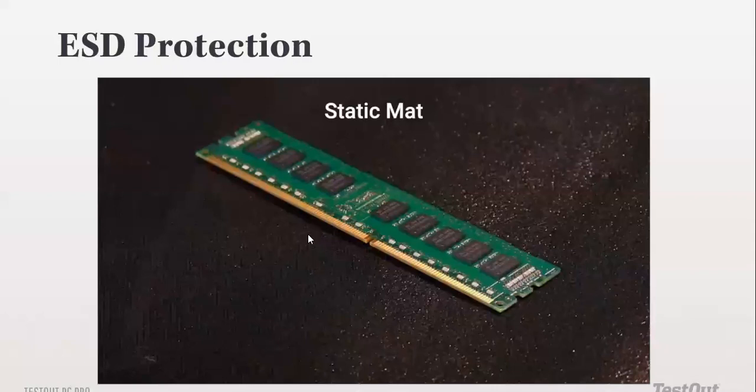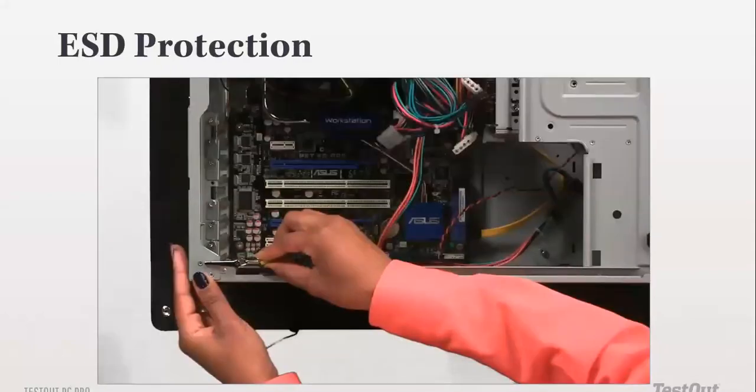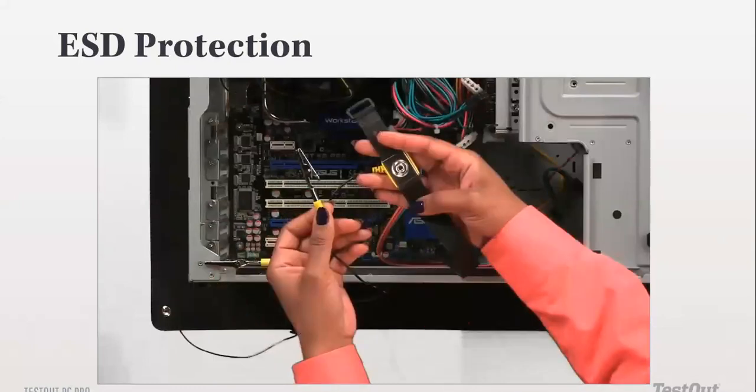There is also another thing that you should implement, which is referred to as a wrist strap. Remember, in the very beginning, sorry for those who were not present, we talked about an ESD wrist strap. Something that you wear on your wrist and connect to the PC case. So always make sure that the amount of electricity in you and in the PC case are at an equilibrium. They're at an equal level. There is no need for a discharge.